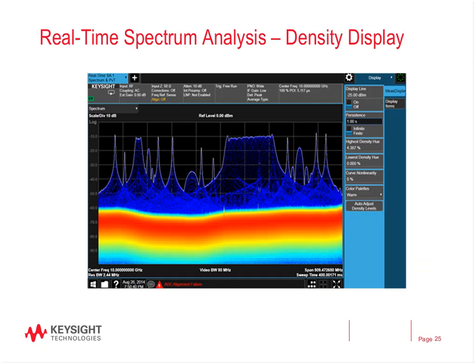Now, that's how it works, but this is how it could be visualized on the screen of a spectrum analyzer. So in this case, we actually color code the signal as it comes into the spectrum analyzer, and depending on how long, it's coded in both frequency and time in terms of the color coding. So the cooler colors are infrequent, whereas the hotter colors in red are actually more frequent. Okay, and so for capturing really elusive signals that maybe only happen in a couple microseconds, you can quickly see them and visualize them with a large degree of persistence on the screen with the color coding. On here, we're showing a capture of 510 megahertz.